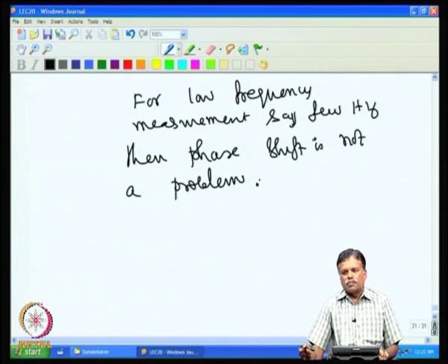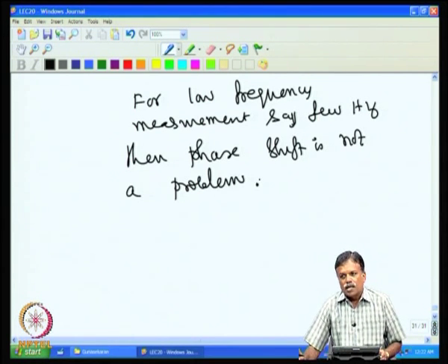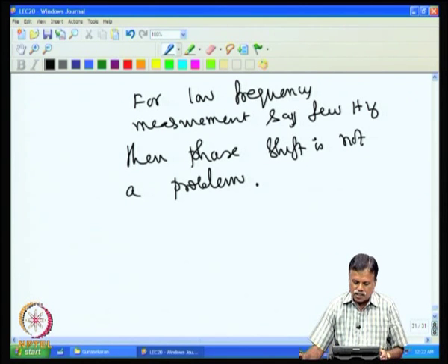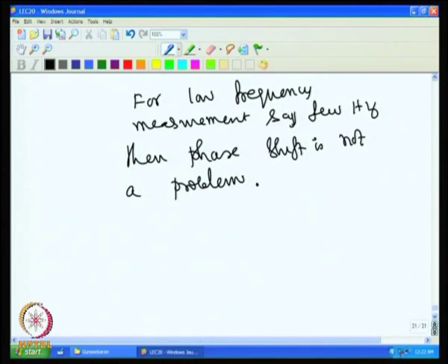So one can use the op amp for automatic balancing, and of course, you will have to measure V1 and V2 to make the measurement accurate, and keep the frequency of the measurement low, so that the error is small.